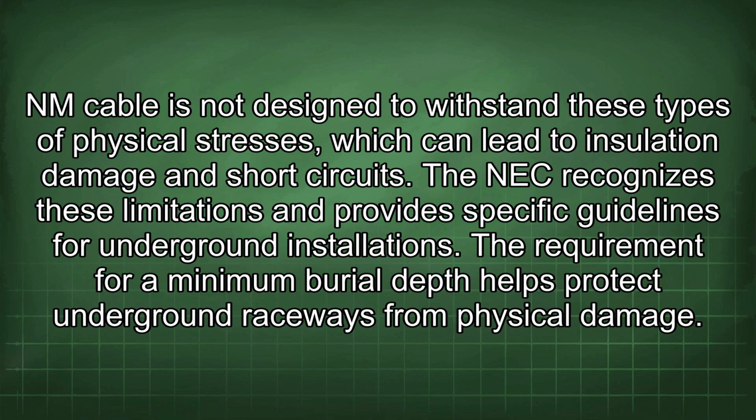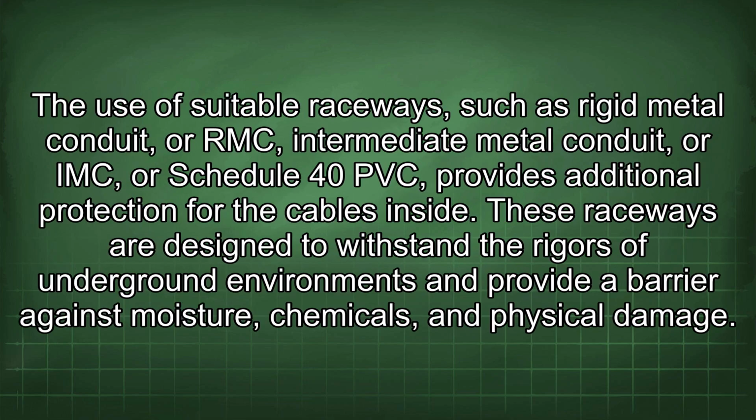The NEC recognizes these limitations and provides specific guidelines for underground installations. The requirement for a minimum burial depth helps protect underground raceways from physical damage. The use of suitable raceways, such as rigid metal conduit, or RMC, intermediate metal conduit, or IMC, or Schedule 40 PVC, provides additional protection for the cables inside. These raceways are designed to withstand the rigors of underground environments and provide a barrier against moisture, chemicals, and physical